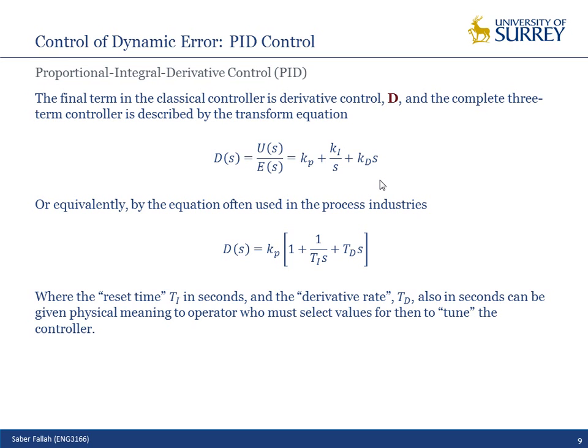This is one reason. If I have a very high rate of change of the input, for example, a sawtooth input, the derivative part will take the derivative of this slope, which is infinite. Again, it damages the response of the system. If I have a smooth input, it is fine. But if I have a random input with a high change rate, it will damage the response of the system.